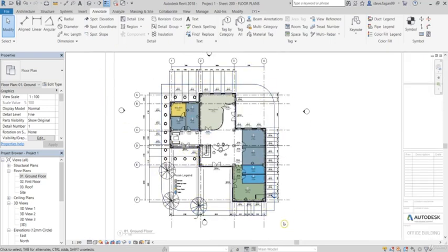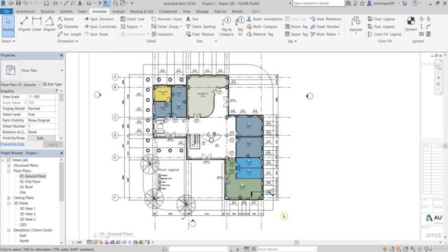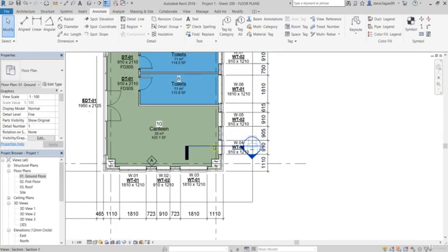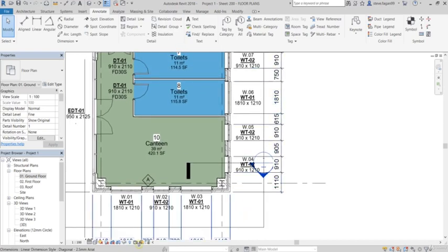What I'm going to do is hide some information. I'm going to reduce down those grid lines so I'm able to fit on another floor plan. So first thing is this section view here. I don't want that to be displayed. So I'm going to come down to my visual controls down the bottom here. I have two tools. First, how I can hide certain objects, and next is where I can reveal them.